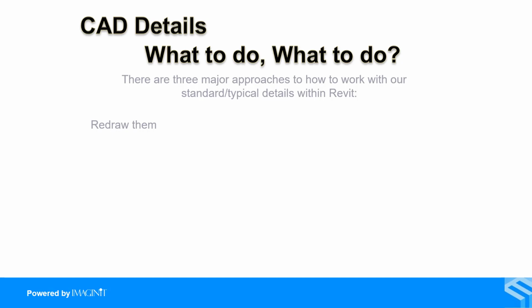To just start by opening up, creating what we would call a container project or a detail Revit project where nothing but your 2D details live. So this would be a container, a library of sorts that we can maintain and use for all our projects, similar to whatever DWGs that you're containing right now with all your details in them.